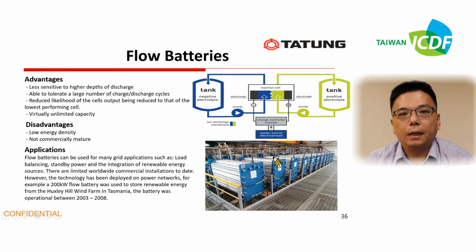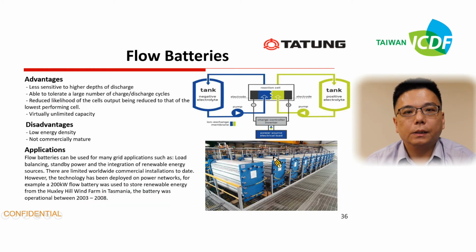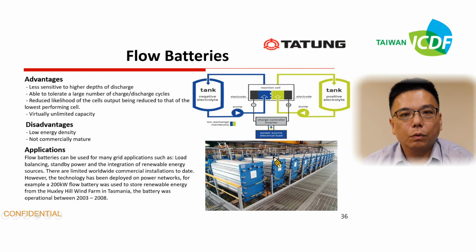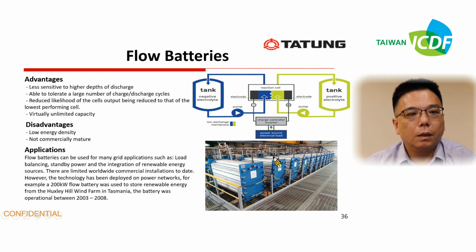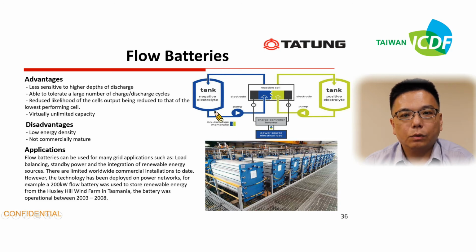And another battery system is the flow battery, especially the vanadium redox flow battery. Its advantage is that it is less sensitive to high depth of discharge. Their electrolytes are always a liquid type.